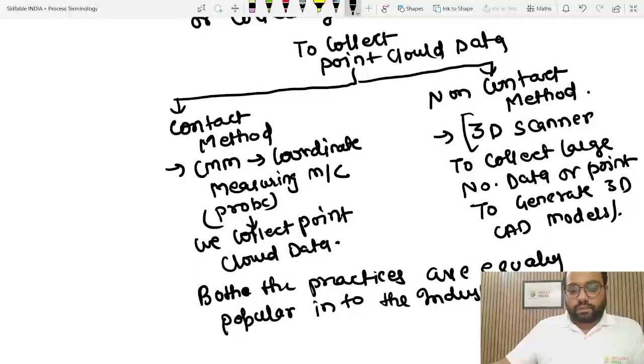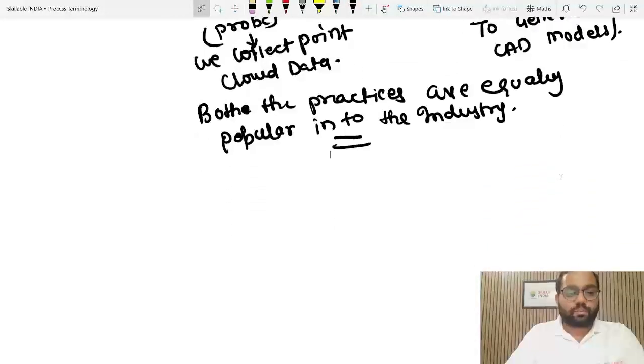Okay, so now we have understood what the methods involved in this are. Now, moreover, we will understand how to collect data using CMM. Okay, so scan the part using a touch probe to get the point cloud data. Obviously, we know we have to touch it. We have to touch the probe to the product to collect the point cloud data.